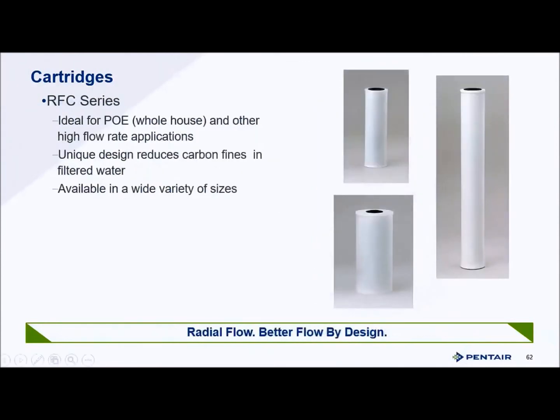Radial flow carbon, this is where the flow comes in from the side. You're going to get better flow characteristics in this design of radial flow GAC units. These are designed for more point of entry applications for taste and odor issues, available in a wide variety of sizes.